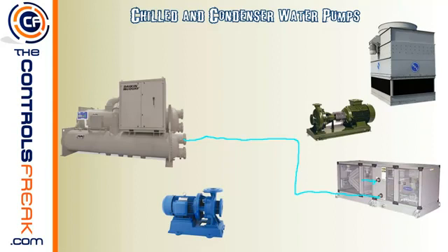It's possible that if you were to supply this coil with water coming in from this direction, the water may not actually fill the coil and you'll get air in it, which would mean you're not going to get cooling on the upper portions of the coil. Water would flow in and then come down and get sucked out the bottom. So the reason why they fill it up from the bottom is that way you make sure you pressurize the coil and get all the air out of that coil. Alright, so we've got the chilled water coming in at the bottom of the coil.